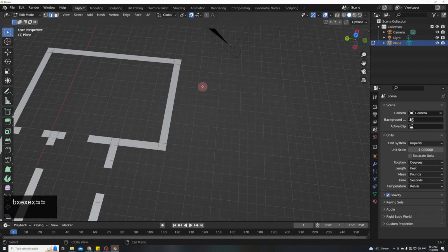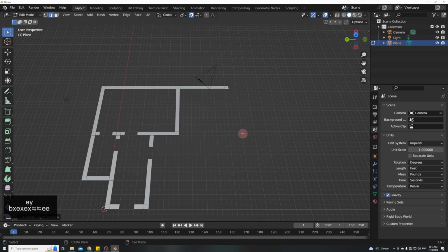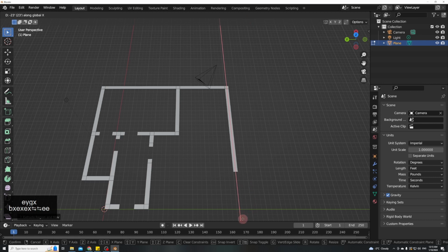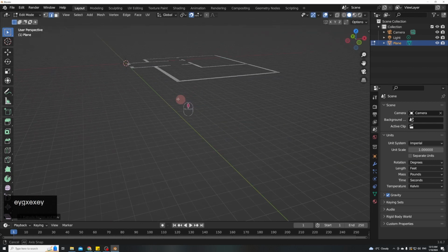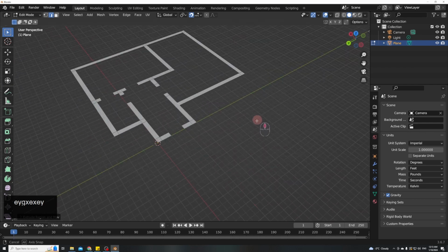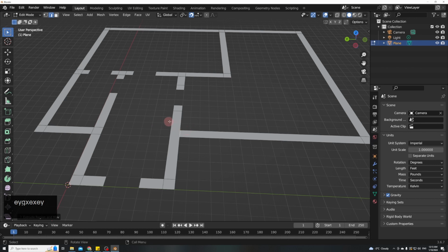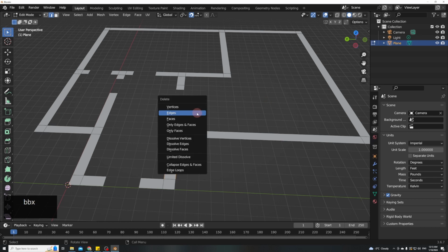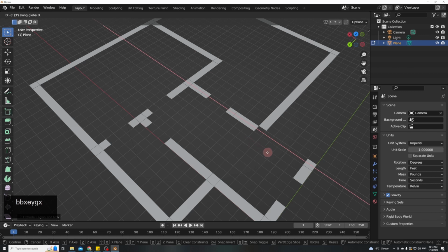Then the last step was the kitchen, like I said. So I'm going to extrude over here, make another column, extrude Y, or no, X, sorry, to come down, and then extrude one more time, and extrude Y again, and all the while making sure it's all flat. I'm not going weird in any misaligned axes. And then I have this same issue again. So do you remember what we do? We select these, just these ones. We're going to delete them. I'm going to extrude along this axis.